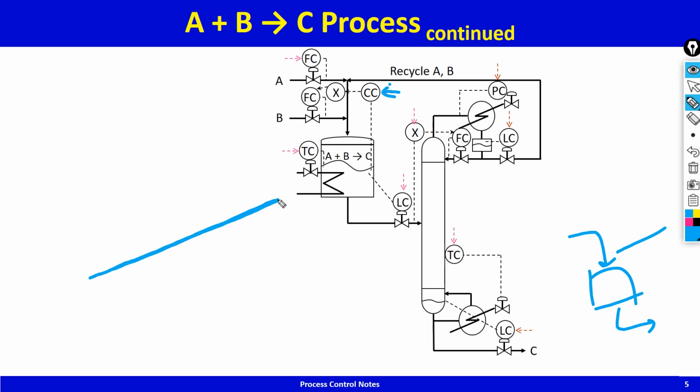So let us say in here we are trying to control B mole fraction, XB is being controlled. We're giving it a set point, and in order to keep the B mole fraction in the reactor at set point, we adjust the fresh A by fresh B ratio, or rather fresh B by fresh A ratio into the process. This control system also closes the stoichiometric imbalance, which was a drifting mode that one had. So this control system will work.